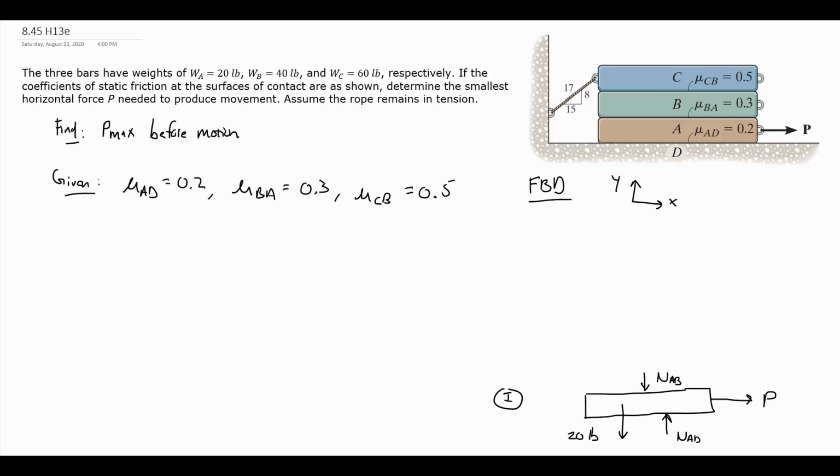I'll actually rename all of these to be in alphabetical order just so everything is consistent and we're not missing anything. All right? And also because bar A and B are not rigidly attached and there is some roughness between them, it's not a smooth surface between A and B, there's friction, so there's going to be a friction force. And friction forces are always going to be parallel to the contacting surfaces, where the normal force is always perpendicular, as we just saw with NAB. It's a horizontal surface, NAB is vertical. It's a horizontal surface, so the friction force is also horizontal.